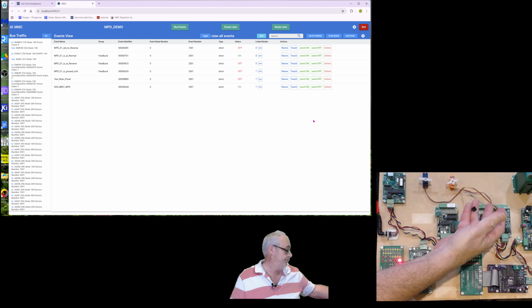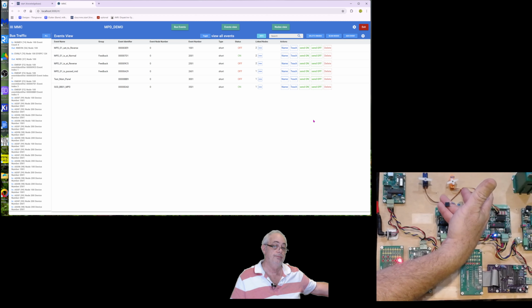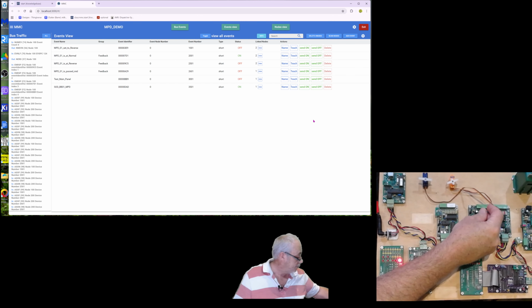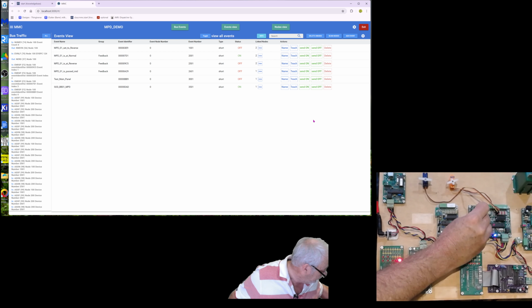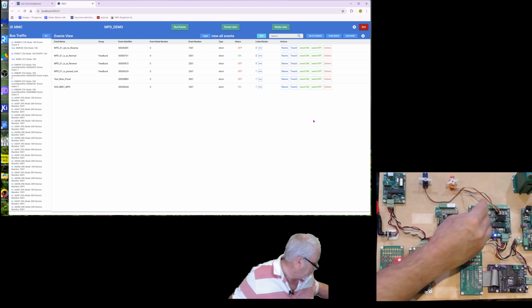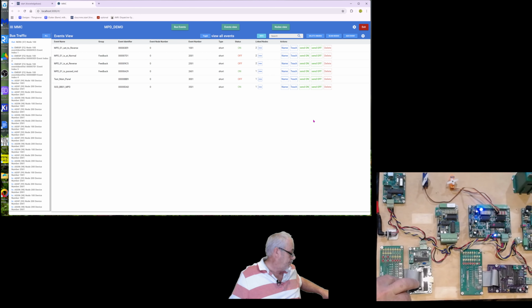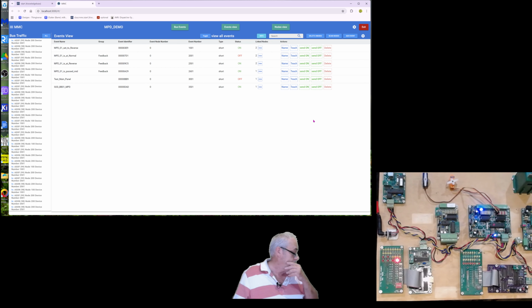It's just an LED soldered onto a 3-pin header. And I plug it across channel 9. And every time I hit the button, it toggles from on to off. Now, in a real railway, that would be connected to the input for my relay.